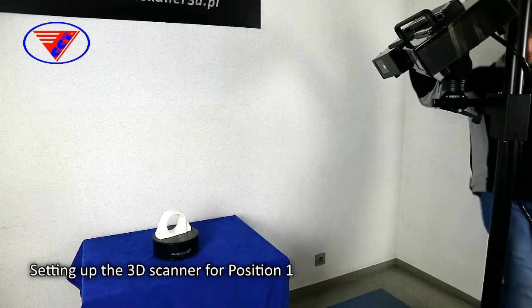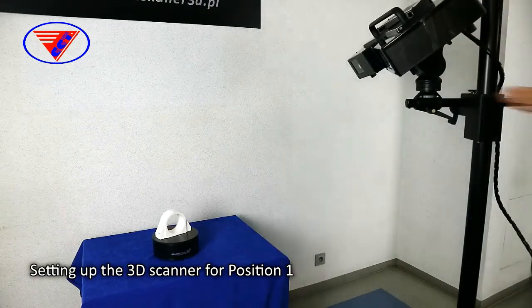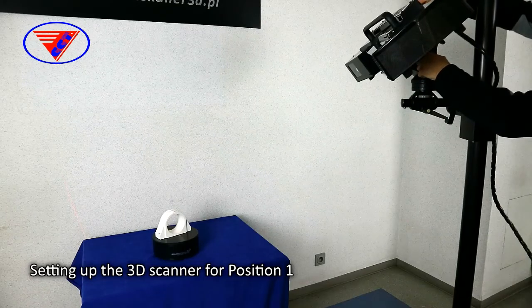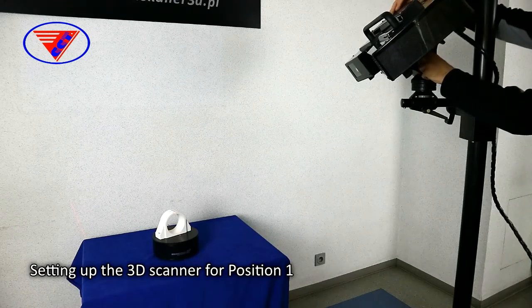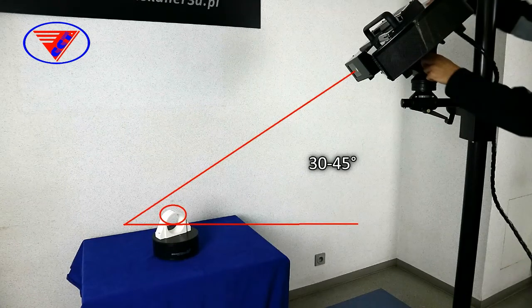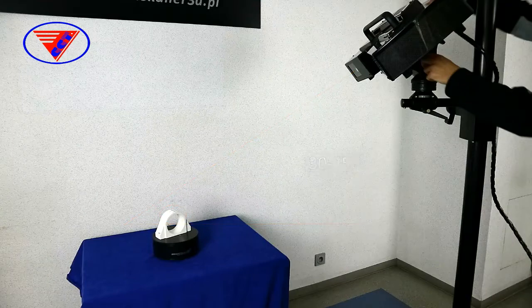First, put the object on the rotary stage for setting up the scanner. Remember about the lasers. Object should be in the middle of the volume, so the lasers should cross in one point. Set up the proper angle of the scanner to the object. To capture the surfaces, the angle from 30 to 45 degrees will be OK.